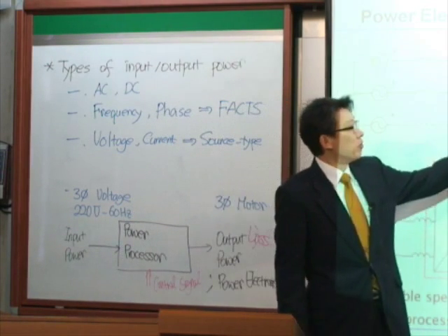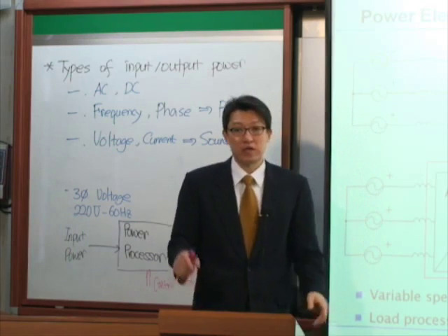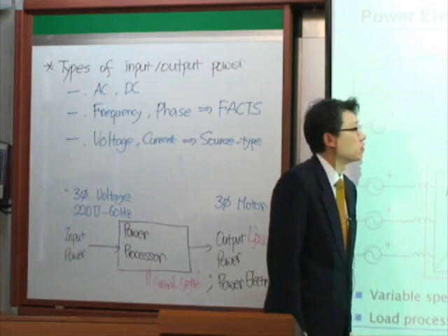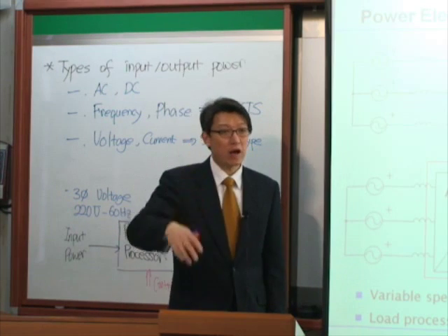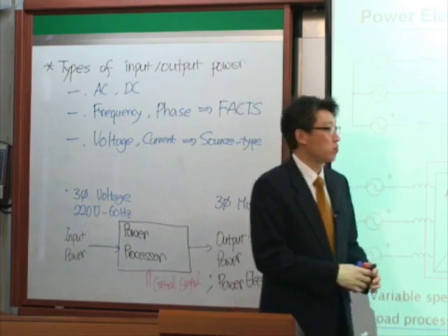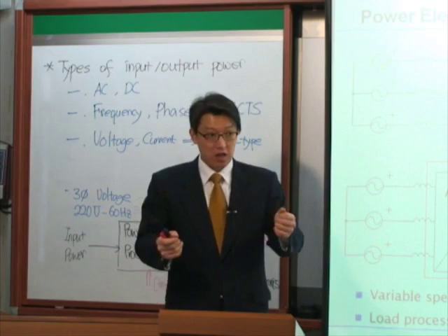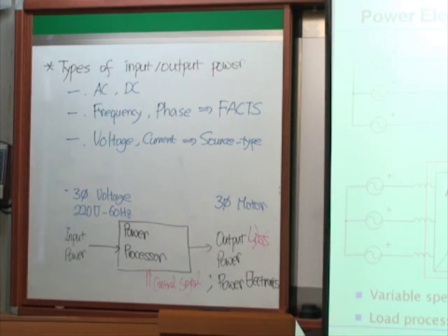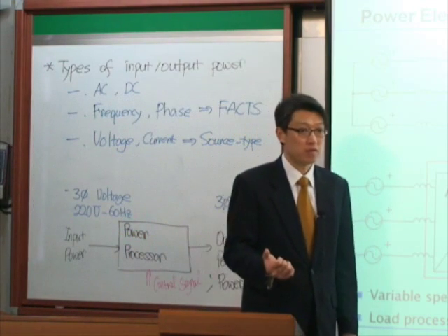But since the motor is hooked up to this fixed voltage and fixed frequency, the motor speed is fixed, okay? Constant speed. The fan is blowing constant, okay? Then how can you control the amount of hot air? By so-called mechanical valve or damper, okay? You have to rotate the valve, or like every room has this kind of radiator valve, right? Here, you rotate this and control the amount of airflow or liquid flow, okay, fluid flow.